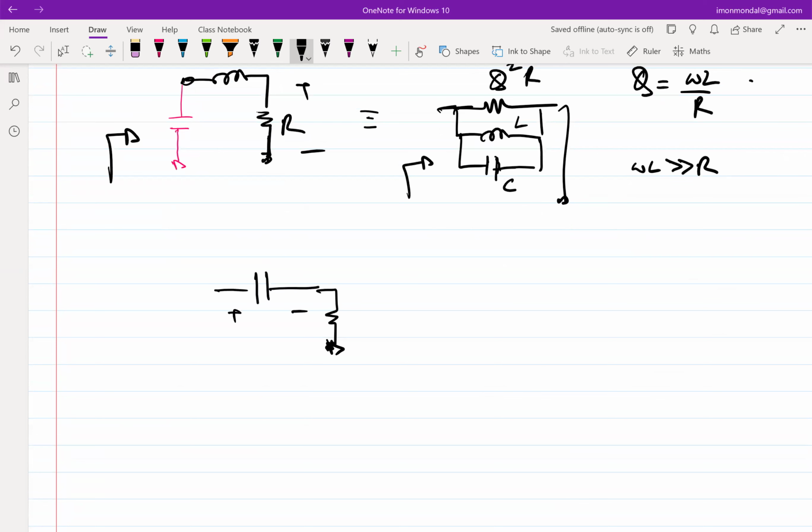I want high impedance here, right? So if I do not want that constraint, then I have to put some capacitive network here so that the impedance looking here for the capacitive network is much lower than the R. I want to get rid of that constraint of the capacitor imposing a higher limit. Then I have to ensure that the step down happens independent of R in some way. Right now, R is playing a role in the step down ratio.